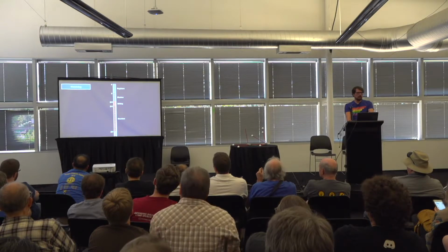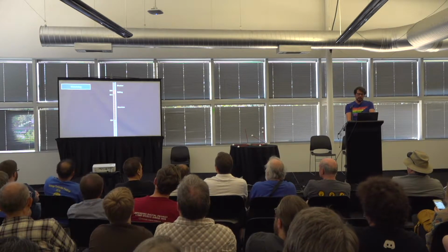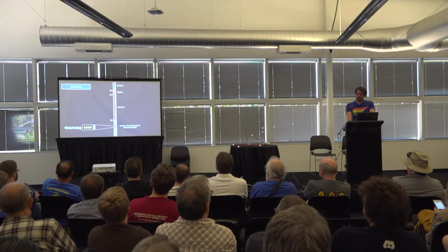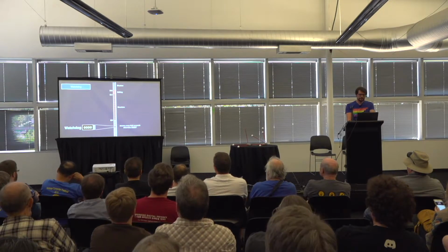There's one more special memory location. At hex 37, the Watchdog. This location needs to be read from or written to at least every 0.64 seconds. Otherwise, the hardware will decide the system software is unresponsive and cause a reset.